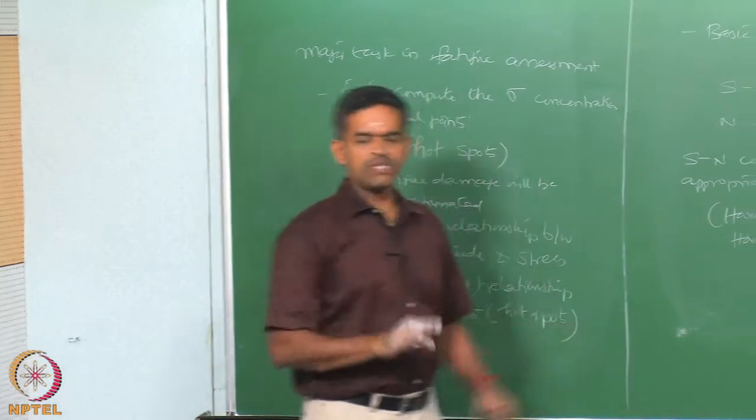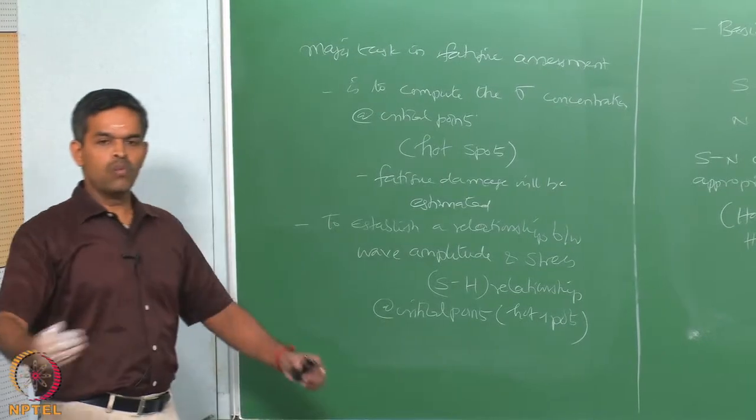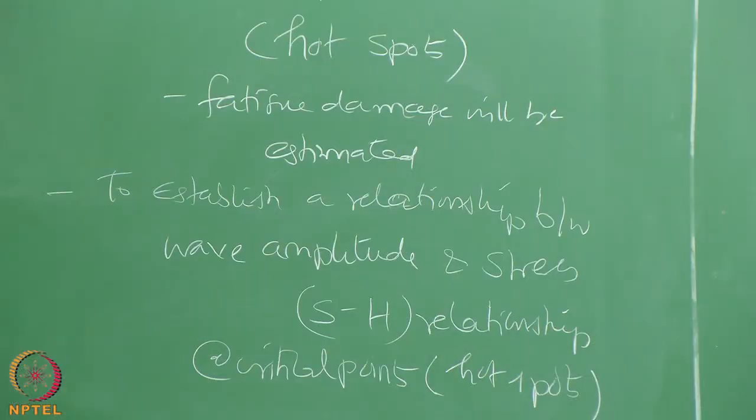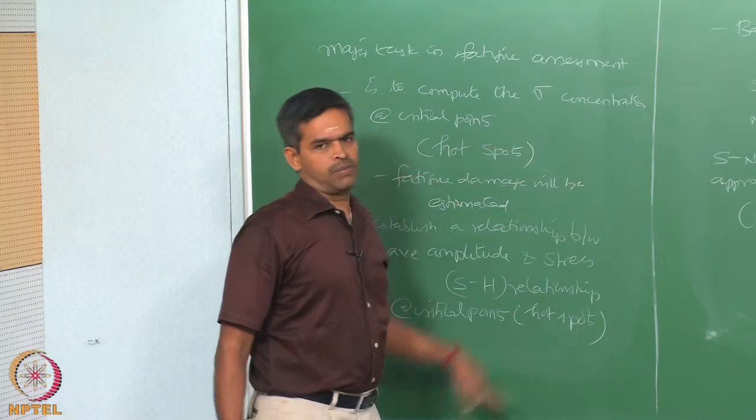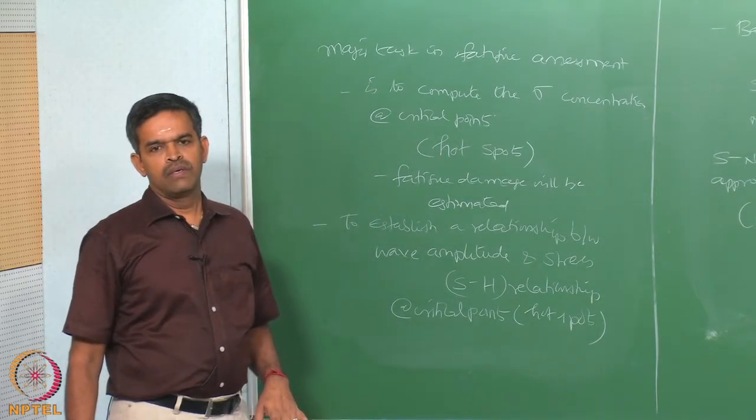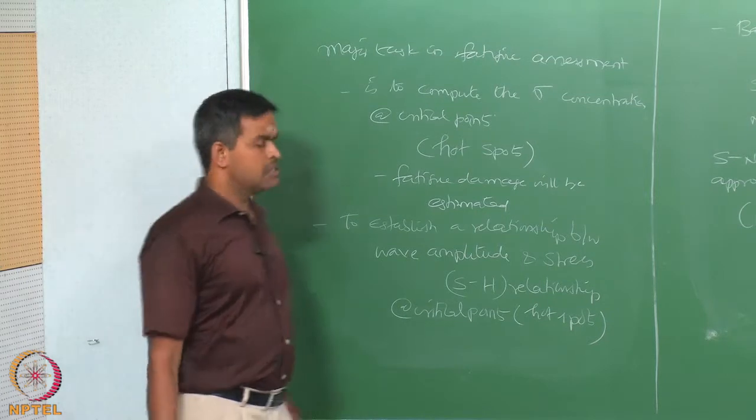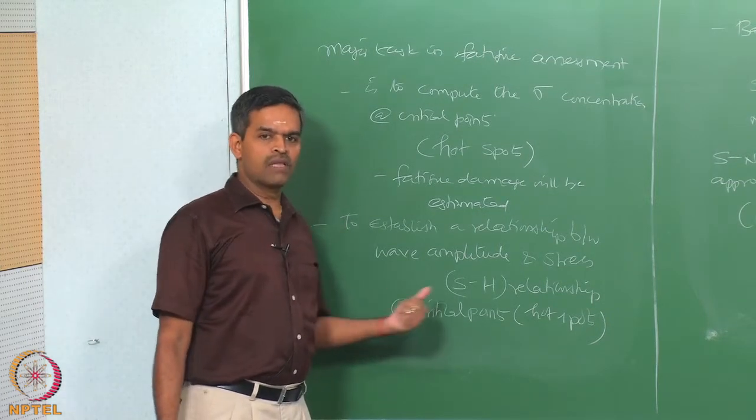So, the whole exercise of fatigue assessment is converged to estimating or computing the stress concentration at hot spots. So, we need to establish a relationship between the stress and the wave amplitude.